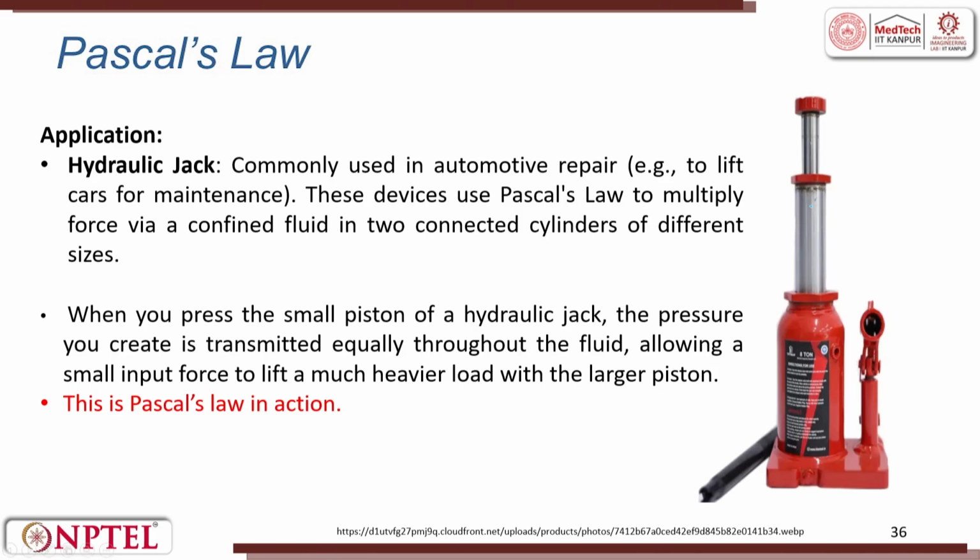So, this is the hydraulic jack which is commonly used in automobile repair. This device uses Pascal's law to multiply the force by a confined fluid in two connected cylinders, 1 and 2, over a different cross-section area. The cross-section area changes. When you press the small piston of a hydraulic jack, the pressure you create is transmitted equally throughout the fluid, allowing a small input force to lift a very heavy load. So, this is Pascal's law in action.